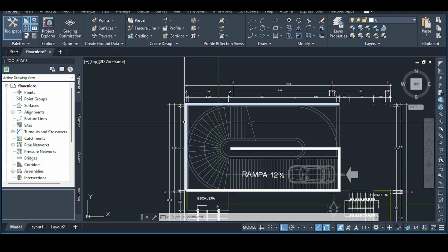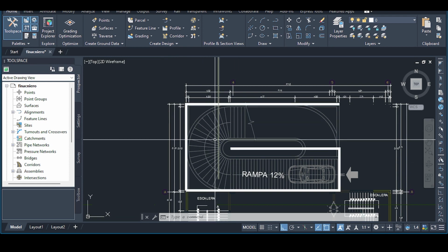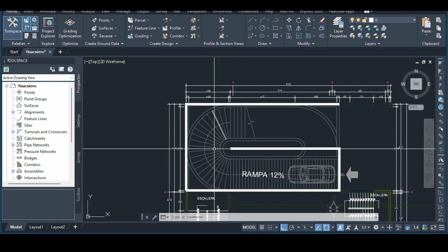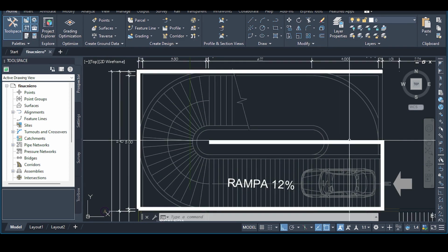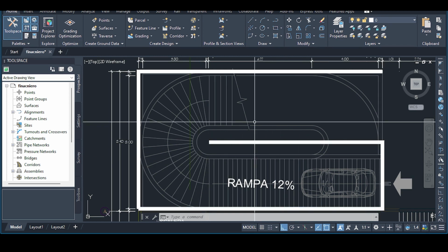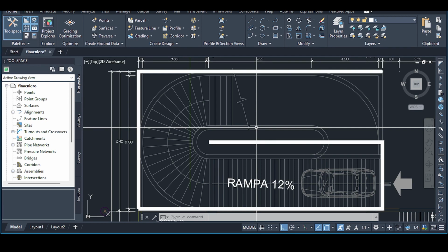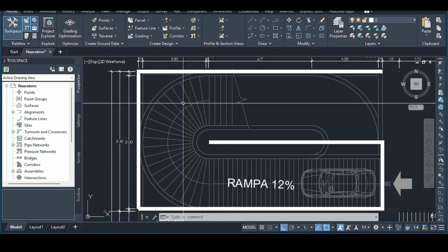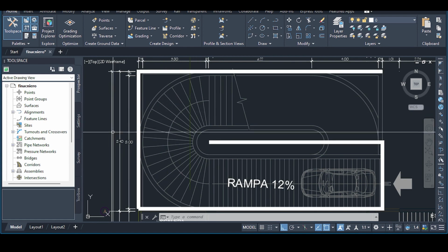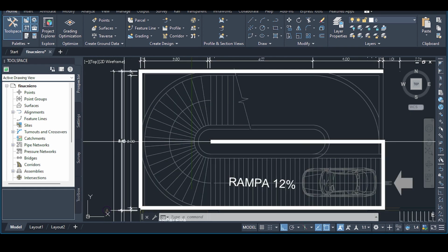Now we are planning still the columns. The ramp itself and the setting out and the layout will be explained in a moment, so just wait for it. But for now, since we are having one-way ramps, I'm planning that I would have a ramp that is adjacent to the other one. This also provides a little bit more turning area and more maneuvering when a car wants to turn, because I somehow am not really happy about those 8 meters. You would have to restrict traffic and allow only certain cars to enter. Anyway, that's my plan, so you need columns for that.